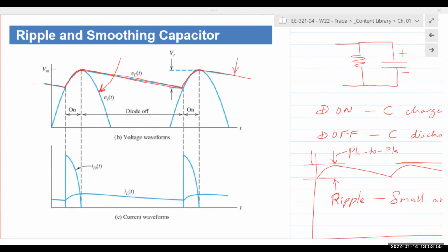Now, when you perform this experiment in the lab, and I particularly like the way this lab has been written for 361, you will take 2 channels of the oscilloscope and connect them across each half cycle. So you can see the positive half cycle being rectified, and you'll also see the negative half cycle being rectified.